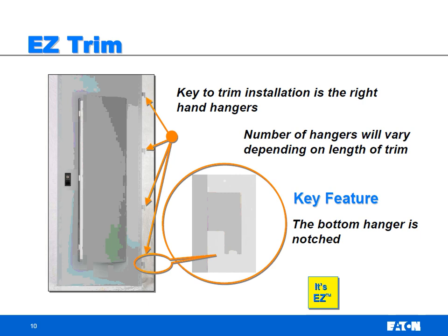As you move it, because it's so heavy, one of the edges goes right into the panel to the hot lugs, and you get yourself into an accident. So I like that door that opens and things that minimize the possibility of electrocution for a maintenance electrician down the road. Yep. And once you put it on the notch, the door feature, you open it on these notches. So you can still open it just like a normal door.